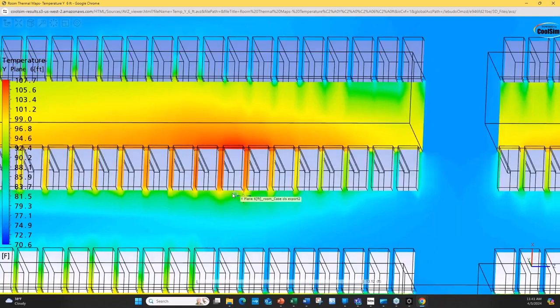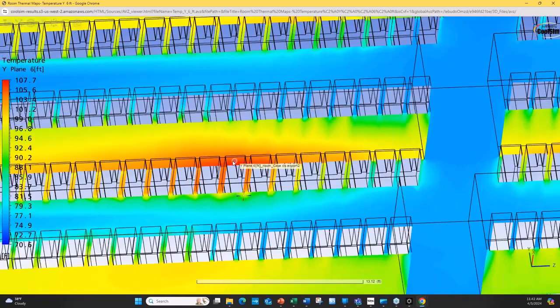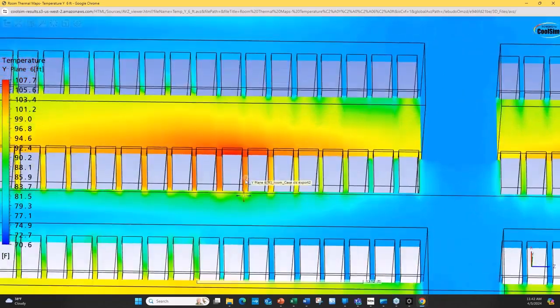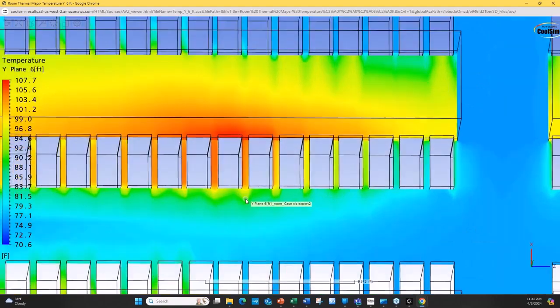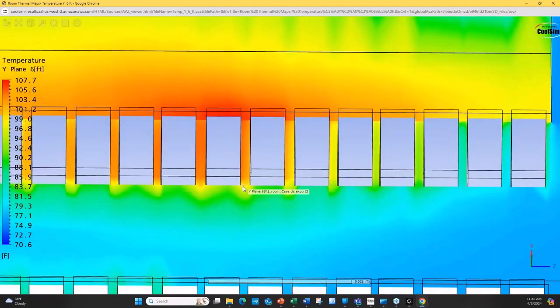What I find sometimes is that the people I'm working with, Magnus, are the design community and not the people doing the IT implementation. So for those of you who are in colos or working for colos or doing this kind of work, it's really important to stress things like proper cable management, proper sealing around the rack, proper sealing under the rack, inside the rack.